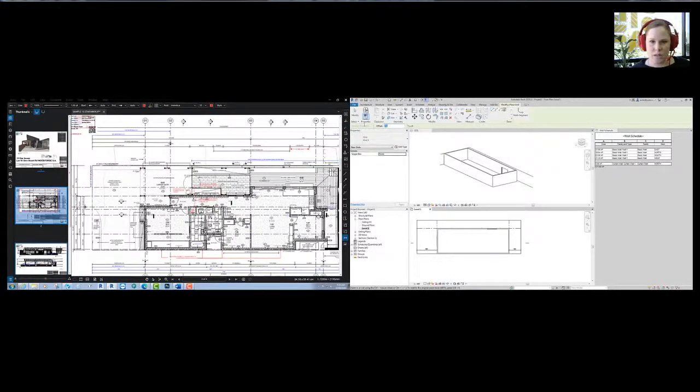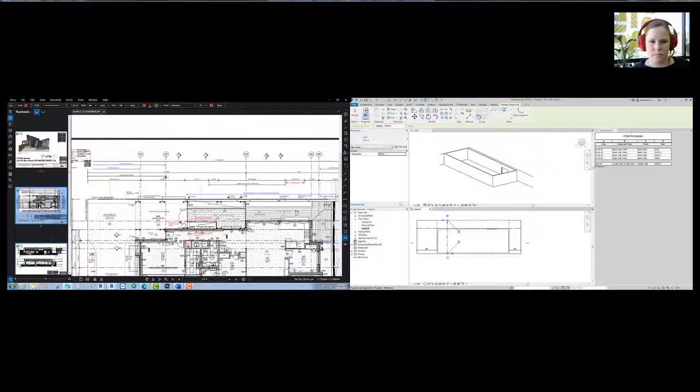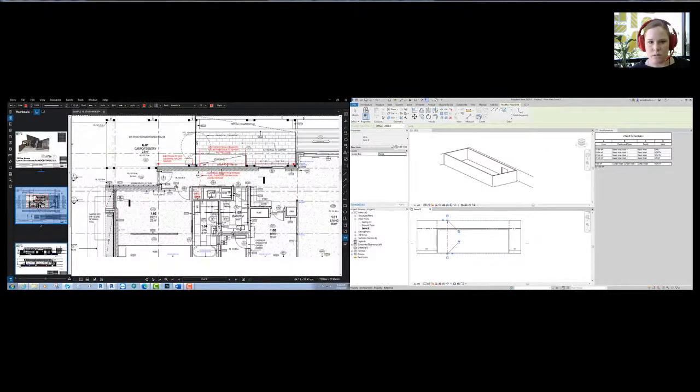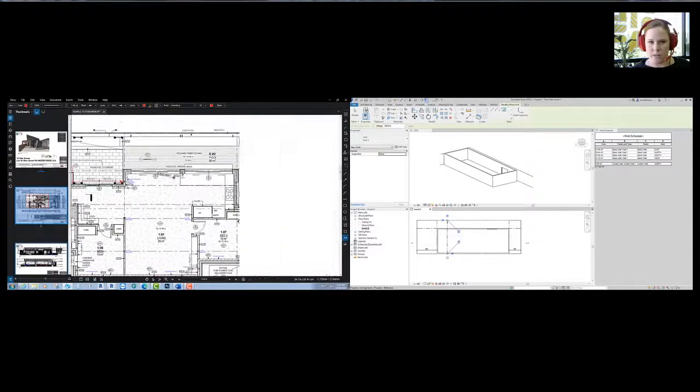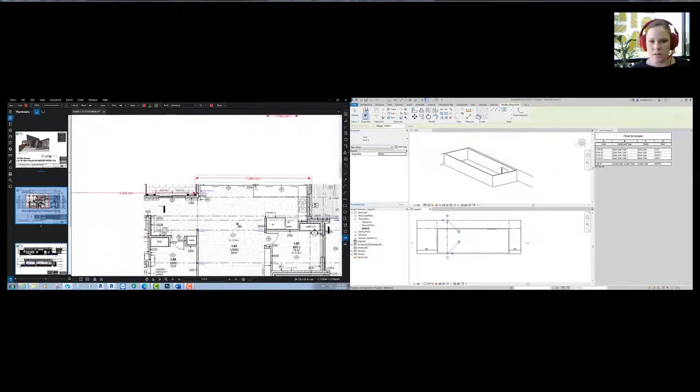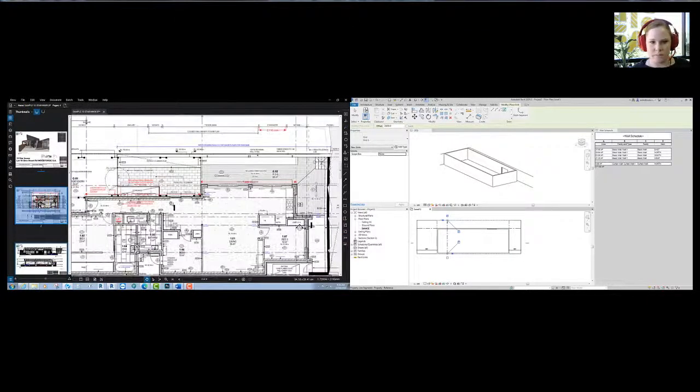Now what I'm going to do is just work out where I want these walls to move to, just using a temporary grid line essentially, and I'm going to offset it the amount that I see on this plan. And this could be done from a hand sketch, so quite often I'll just do it from a hand sketch and then just make some assumptions in terms of the ceiling height in certain areas. Or I can create just a basic volume in Revit like I'm doing now, and then take the values off of that for Hubble.